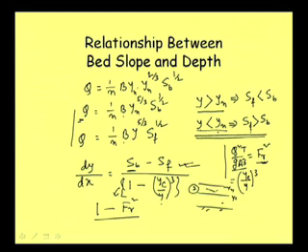At critical flow, Froude number is equal to 1, fine. In subcritical flow, Froude number is less than 1. And in case of supercritical flow, Froude number is greater than 1. Now, when our depth of flow is greater than y c, then it is subcritical condition, Froude number is less than 1, and so Froude number square will again be less than 1, and 1 minus something less than 1 will become positive.